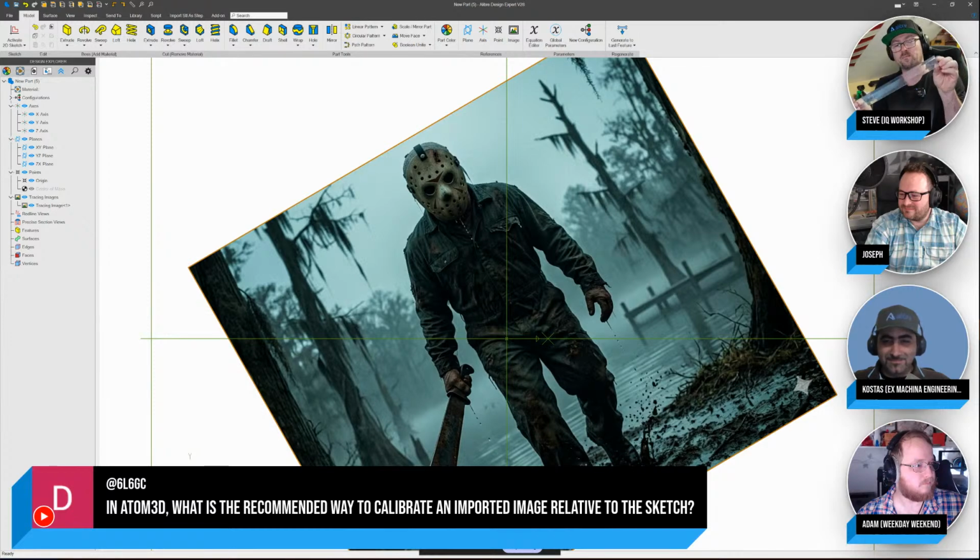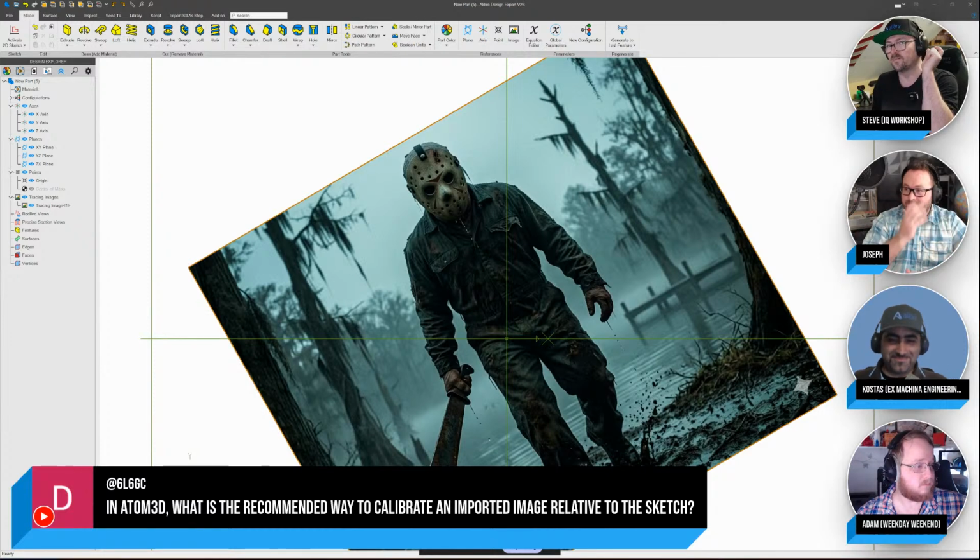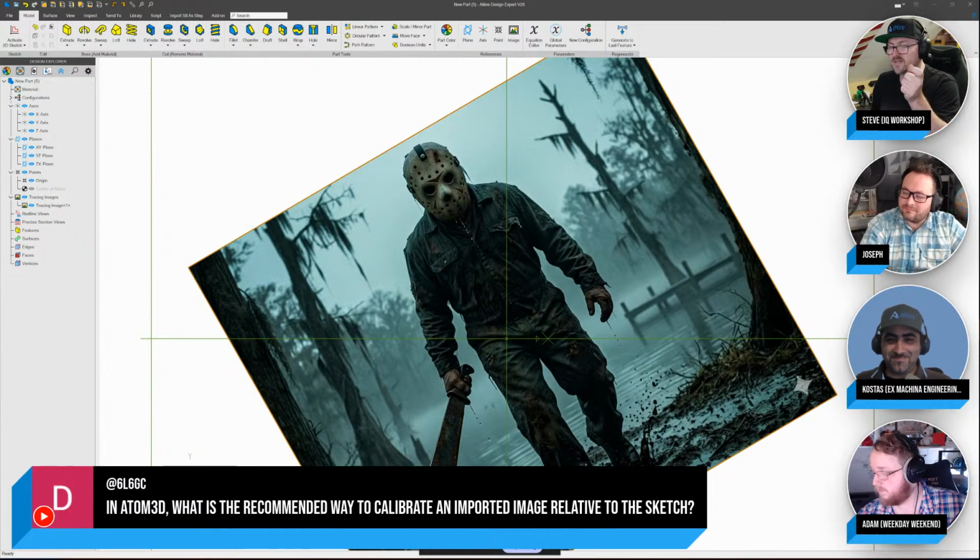And the larger the scale that I use, so this is a 30 centimeter ruler, if I use all of it, the amount of error is reduced the further you go. You know, if you only measured 1 centimeter or 10 millimeters versus 100 millimeters versus 300 millimeters, the factor of your error reduces. So that's the first tip.